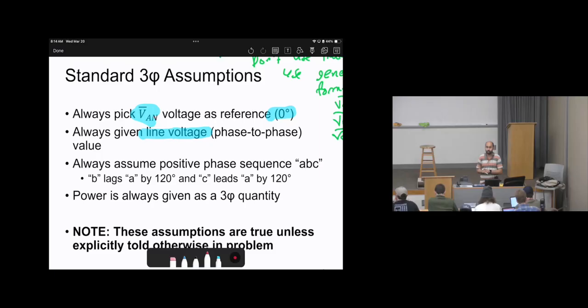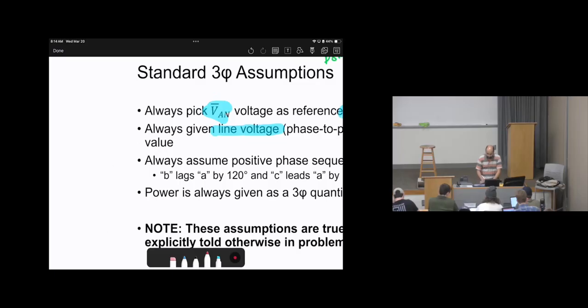The default, if there is no information or indication saying this is V line to line or this is V line to neutral, is that this is V line to line. So when we see any label, it says V line to line equals this value. We used to say, for example, a system has 500 kilovolts without mentioning anything. So you will say V line to line equals 500 kilovolts. Then what should I do? You will say V line to neutral equals V line to line over square root of 3.